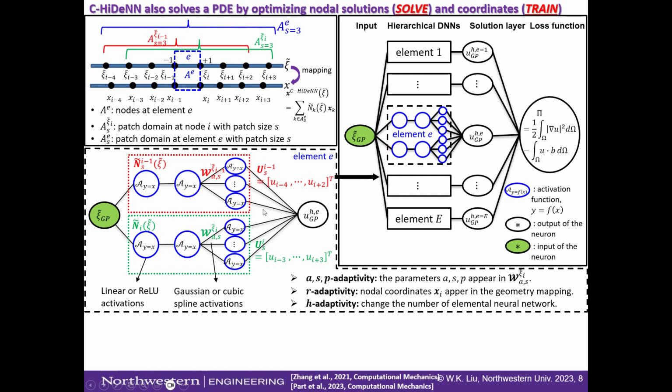And this is very different from the standard higher order finite element methods, because in higher order finite element, they increase the elementary degrees of freedom and construct a higher order Lagrange polynomial, Lagrange shape functions for that element, that leads to the increase of the global degrees of freedom.